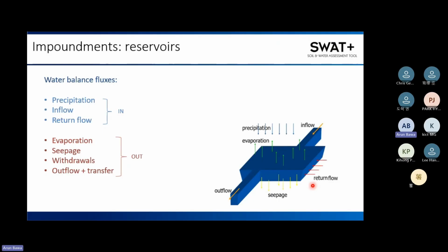If else, if my soil water condition is this, then irrigate with this one. You can put in as many conditions as you want with those decision tables, so you can control each of these water structures or any object in SWAT+ in great detail. So this is the reservoirs: it can have many inflows, one outflow.